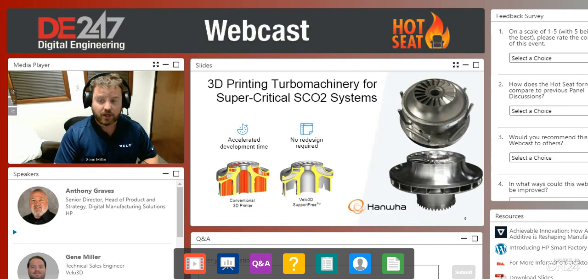We're very well poised to print shrouded impellers and rotational machinery. Sometimes in commodity manufacturing or commodity additive, you would have to tilt this and you'd lose roundness of the part, and you'd have trouble balancing it and rotating it in your final application. Because we can print these flat without any supports, it's just a very easy, simple post-machining operation and then a final application.